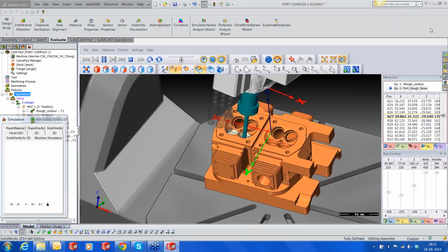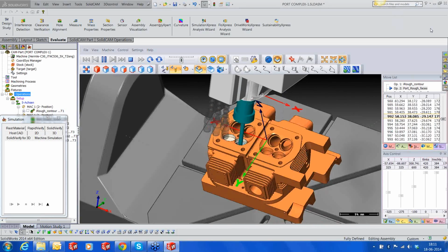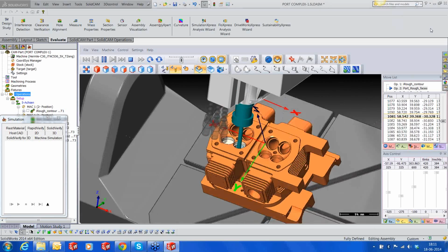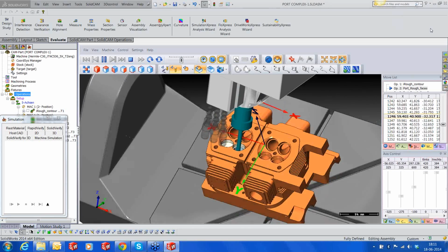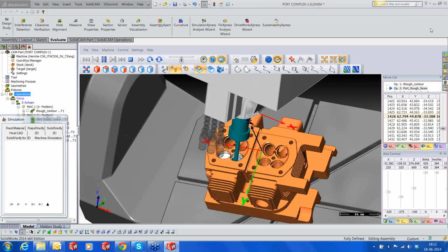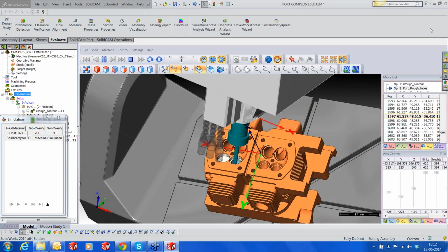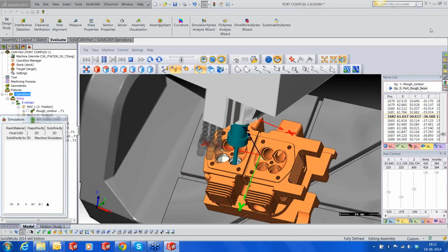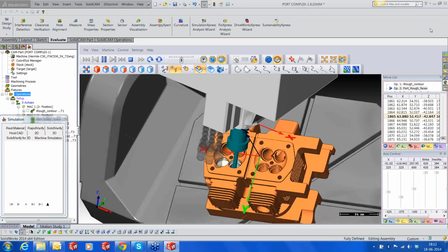These movements are probably the reason why we don't recommend usage of end mills, because the amount of tilt you're going to have is tremendous as it starts approaching inside. The only cutter that is probably capable of handling these tilts and the swings is a ball nose kind of cutter. You have got a spherical type of surface that can maneuver itself all the way down.